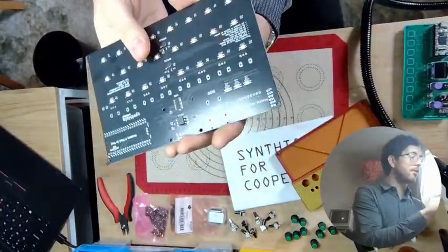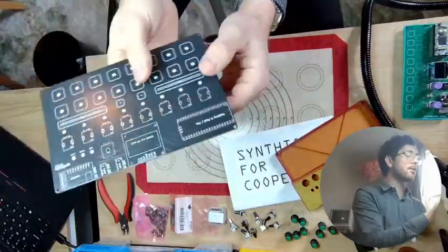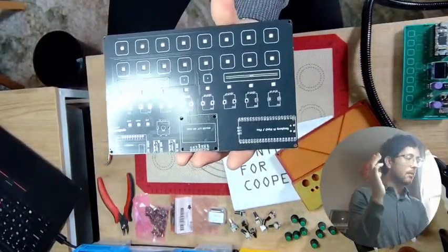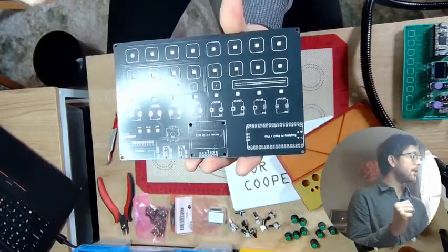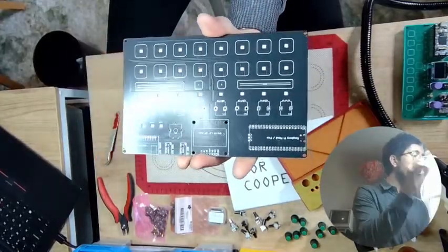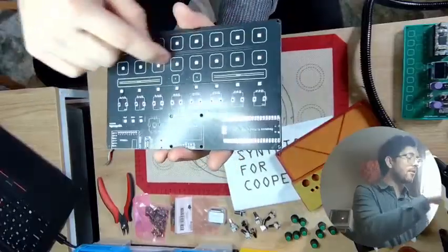Okay, and then we have a bunch of area for pots here, up to 8 pots. I believe there's a little chip here, the 4051 classic analog multiplexer, so you can use all 8 pots. I think normally the Pico can only handle 4 ADCs at a time, so you kind of have to switch between the banks, is my guess. And we have a little encoder spot, and you'll notice there's a ton of LEDs, right?